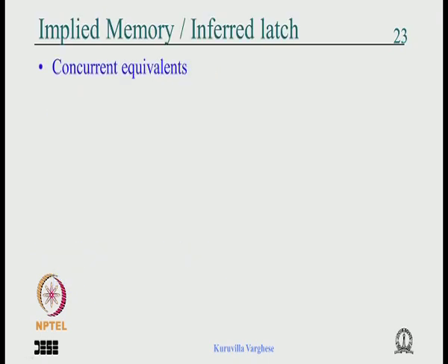But the question is, can we have a latch in a concurrent statement? Concurrent statements like with select and when else. The answer is yes, at least in the case of when else, because it is equivalent to if then. You say output is something when some condition is met, and instead of saying else, you keep quiet, you don't state that, then you get an implied memory or inferred latch in a concurrent statement. Or in the with select case, you specify a condition, a decode, and you don't specify anything else, then you get a latch.